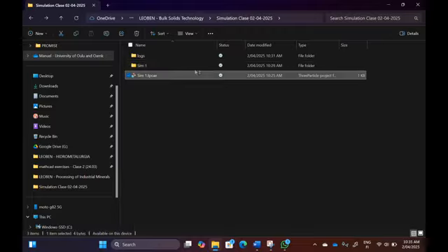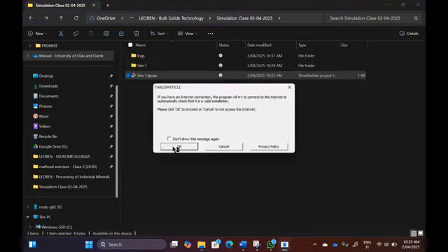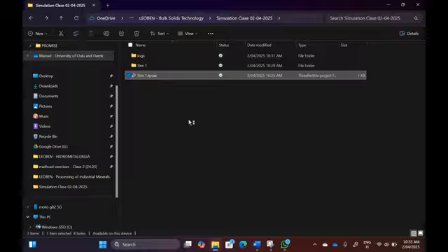You didn't get the TPCAE file either. Did you have a long file path, a long folder structure? Yeah, that's why I wanted to ask you if too many folders affect the processing. Probably, yeah. It's better if it's a very narrow structure and sticking to ASCII code. So it's easier to work, let's say, on E double point simulation rather than on desktop, a folder inside of desktop and go on, because then the structure is getting very long.